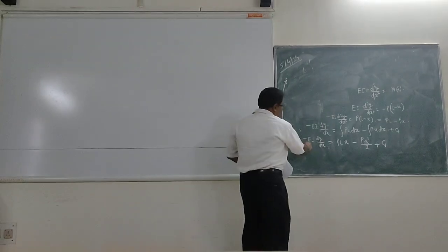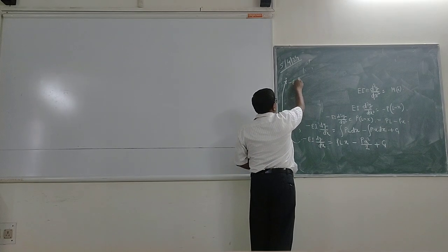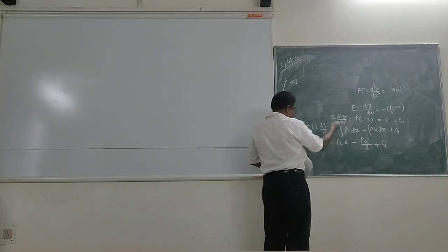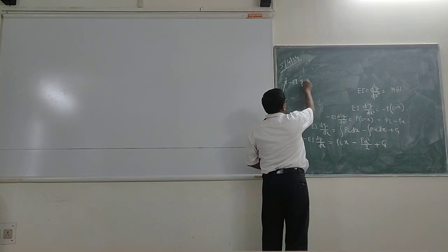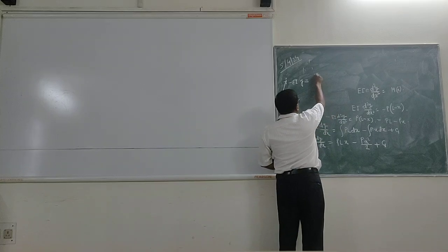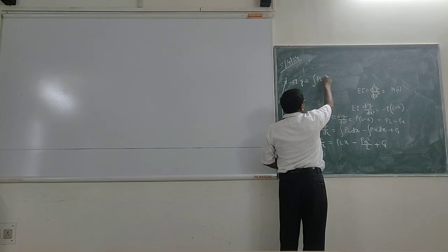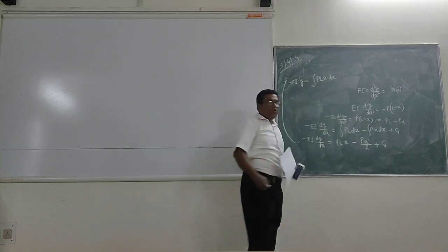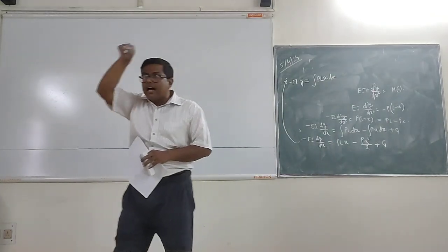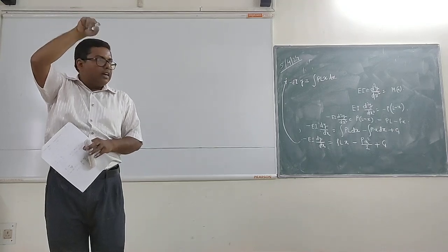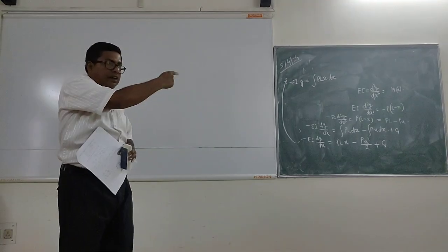So minus EI, dx will be going to the other side, so it will become EIy equal to the double integration of PLx dx. You see, we have put a double integral sign. You remember, while formulating, we have put a double integral sign. You understood?